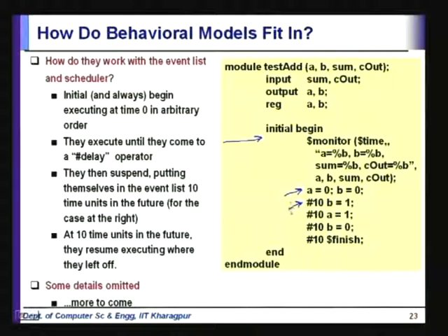Because Verilog is not just one procedure like this, there are several modules which are there, and because this is hardware we are talking about, they are all there in parallel, right. But we have to simulate the thing in a single processor. So, we have to treat them as concurrent, because physically in hardware they are all going to be really parallel, but in simulation we cannot have that. So, we are going to do that serially, but we have to maintain certain guidelines so that the final outcome is consistent with the actual hardware, right.